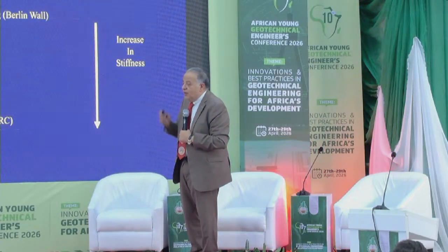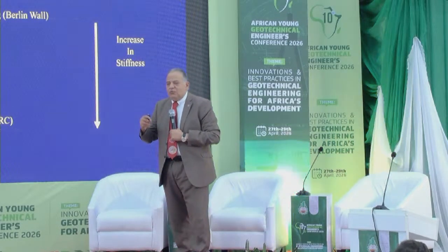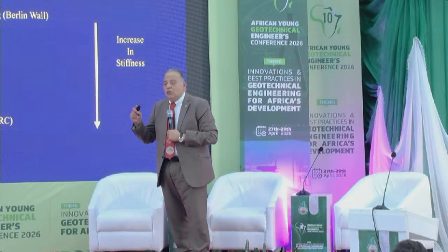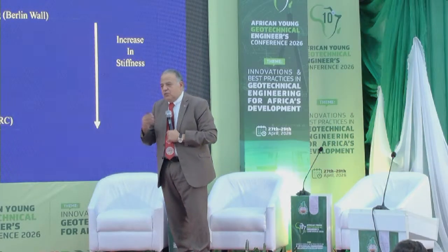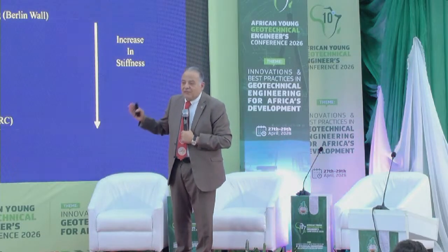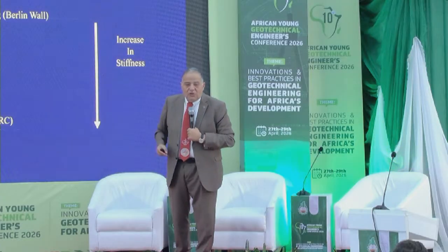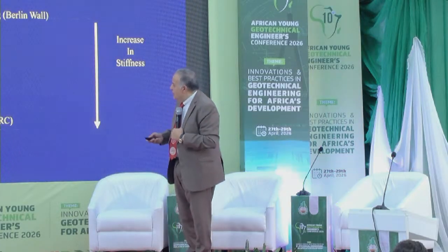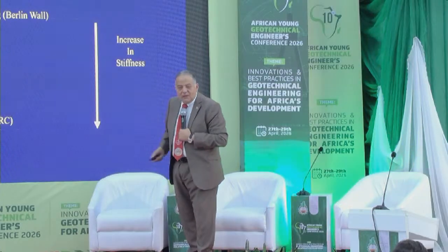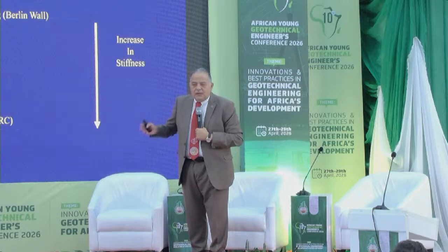And even in the piles, depending on the diameter of the piles used, we will have different stiffness. We have to remember that most of the early measurements that we have in excavations were based on the Berlin wall. At the time, it was not popular to have piles or diaphragm walls when they collected the measurements. So at the time, it was soldier pile with wood lagging. This was the system that they collected measurements for.